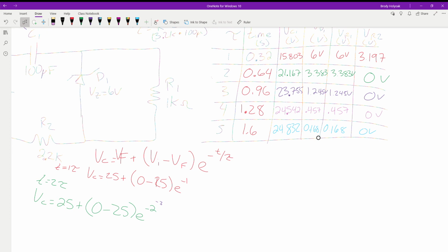At some point, yeah. I mean, this voltage is going to have to drop somewhere, and you don't want it dropping on your supply. So in this instance, for the timing, no, you could get by without it. But with how the circuit's set up, you're going to be loading up your supply, which could short things out in the end.